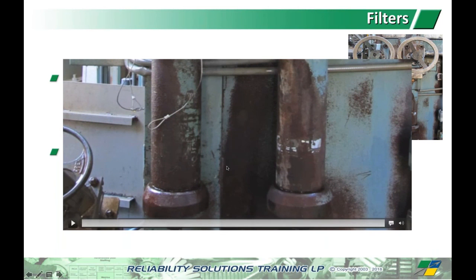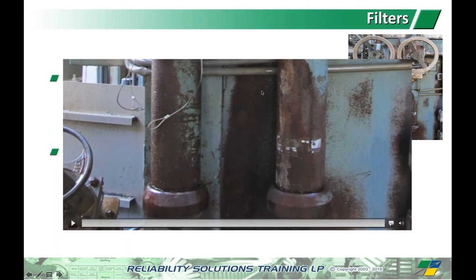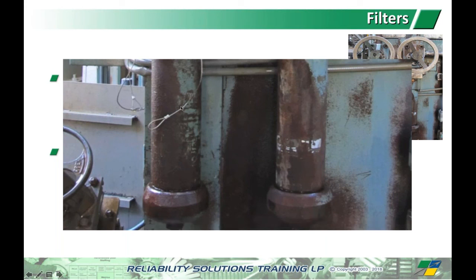What we're listening to there is the head of these bypass filters that you saw in the video. And what was happening is this was on that same system with the accumulators. When this pressure diffuser fired, there was a tremendous amount of flow through the system. And the flow was too much for these filters, and so they went into bypass. What had happened here is the system originally was designed correctly, but they'd upped the stroke rate and done some other things to the diffuser.